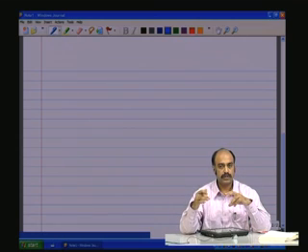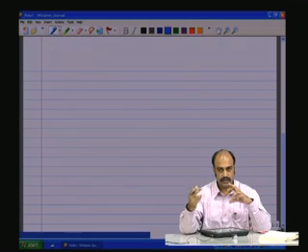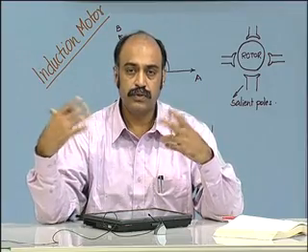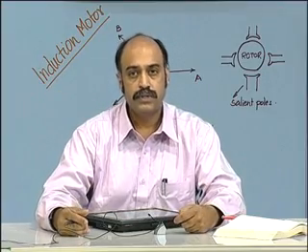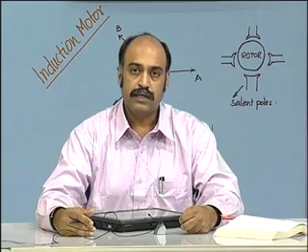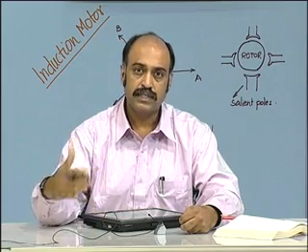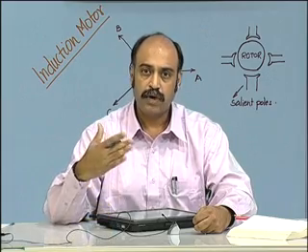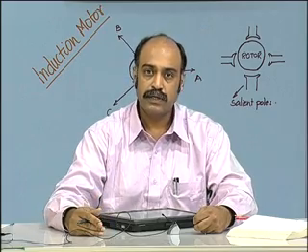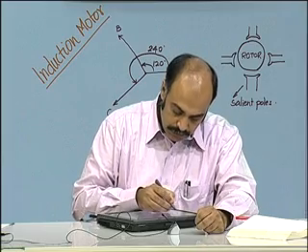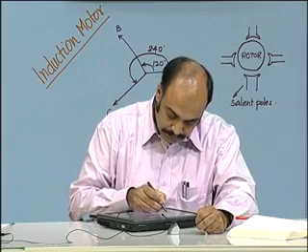and the shaft of the induction motor is connected of course to the rotor, and the rotor is rotating in the magnetic field, and that is going to induce the voltages on the stator side, which is connected to the load or to an AC source, thereby putting the active power into the source. So the way the energy flows would be in this fashion.